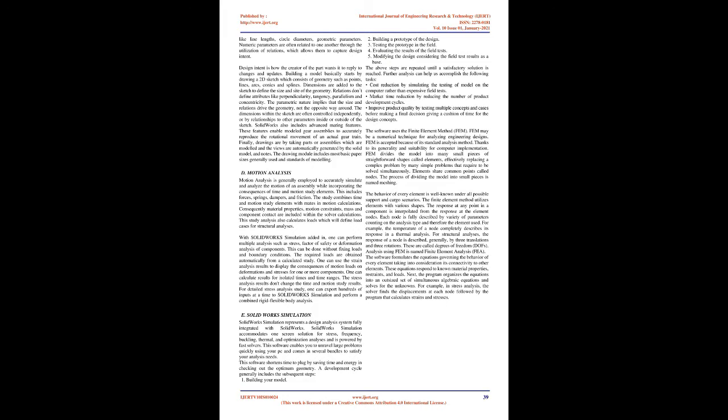In our work we aim to design a serial robot which is suitable for welding application for curved profiles, where forward kinematics and inverse kinematics are calculated and simulation of end effector is done for given joint and link parameters, and final workspace of the arm is identified and graphs associated with motion of the manipulator as a time sequence of joints and links are achieved using RoboAnalyzer software.